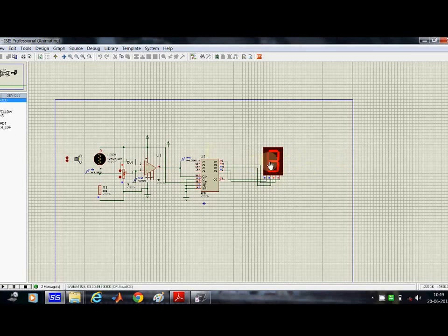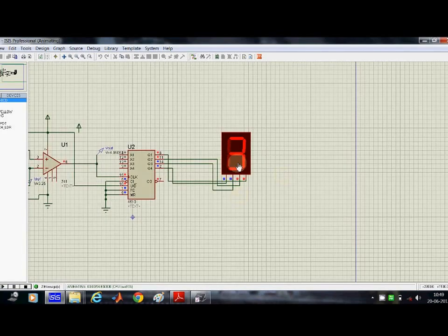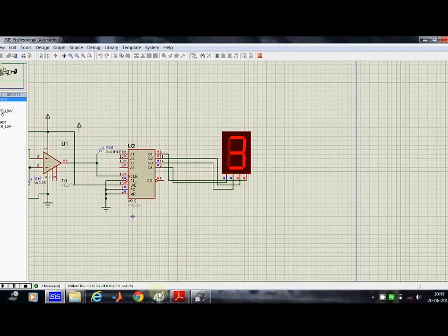But there is still one more step to go. We have to design the output as well, because in the simulation I was having a 7 segment display which can directly display from the binary coded decimal, but we need a decoder such that this binary coded decimal can be decoded into the 7 segment display.